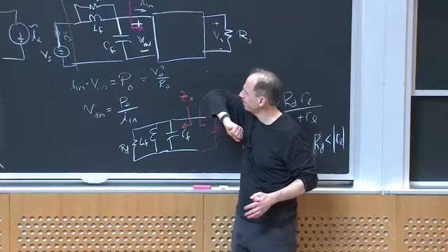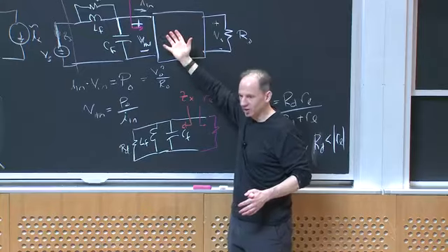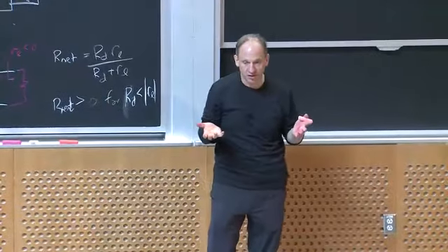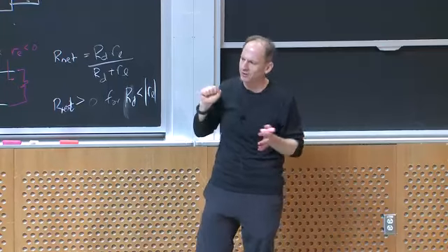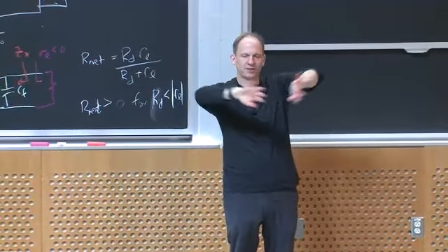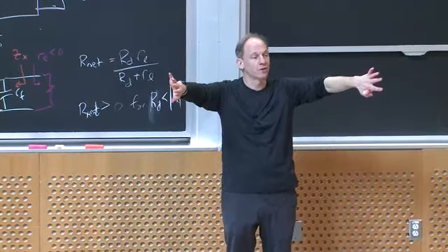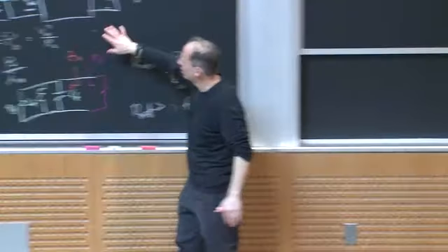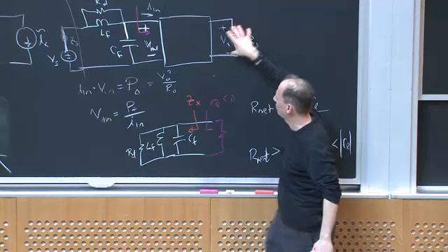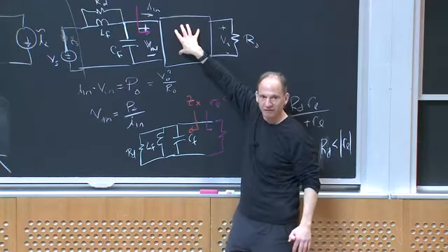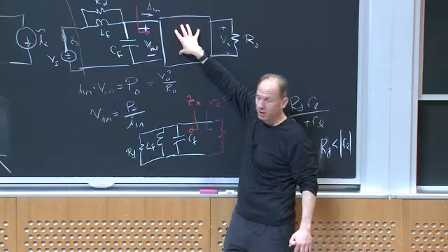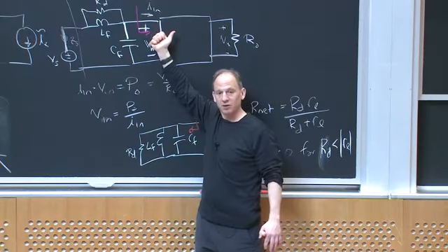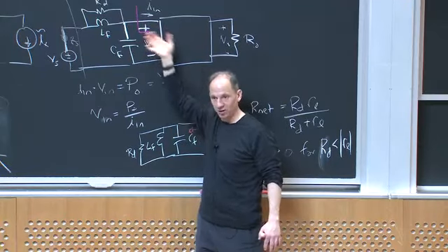But what they showed is an additional sufficient condition, although not necessary to getting a stable system, for being able to ignore the design of the filter, or decouple the design of the filter from the design of your controller for your converter. Imagine that instead of a perfect controller over the output, I just regulated my converter at fixed duty ratio, and I looked at the input impedance of the converter at fixed duty ratio across frequency, which is going to vary.